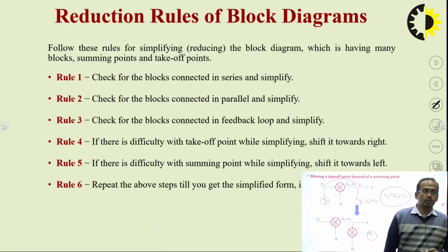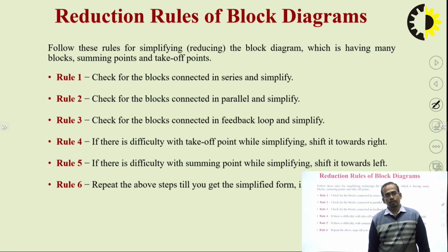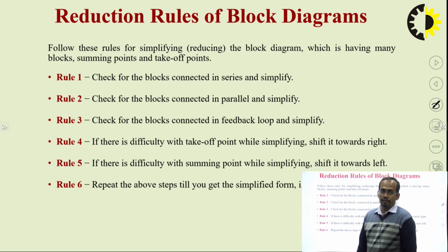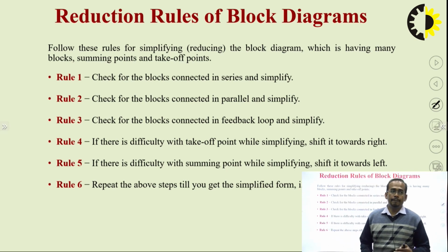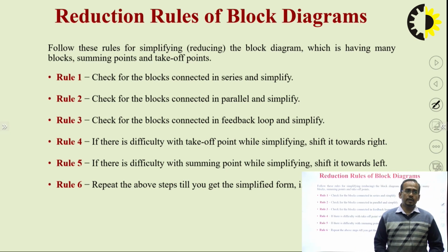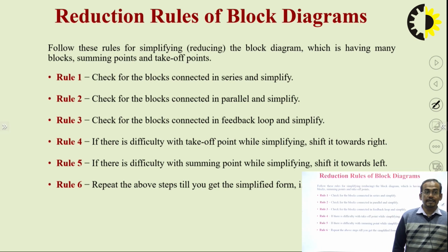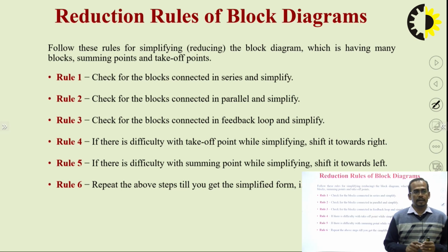So these are the rules for reduction of block diagram. You have to follow these rules for simplifying the block diagram which has many blocks, summing points and takeoff points. So the first rule is to check for the blocks connected in series and simplify. First you have to identify how many blocks are connected in series or cascaded, and you have to simplify.